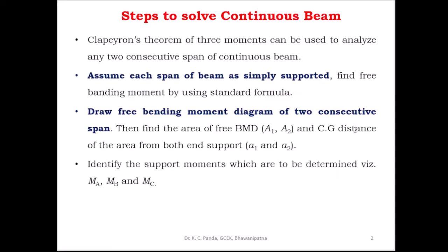Then what is a continuous beam? A beam which is supported on more than two supports or more than one span is called a continuous beam. Such a beam, when loaded, deflects in the form of a curve such that at the intermediate supports the slope of the elastic curve for the two spans will be the same.